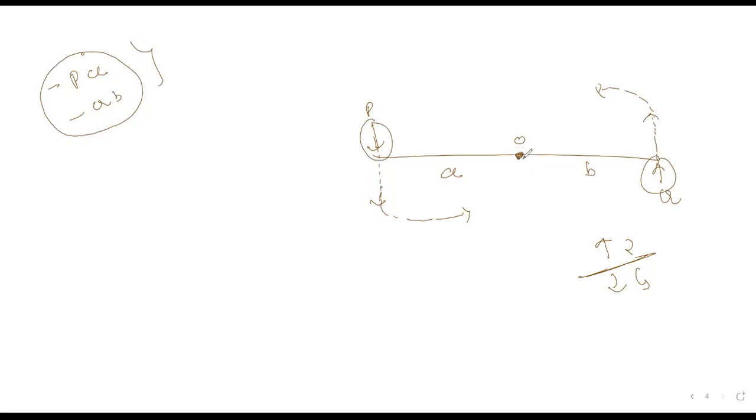Keep in mind, the direction of moment depends on at which point or at which location you are taking a moment. Okay, it depends on that. Fine, both forces have opposite directions, but we are taking a moment about O. Your force is on the left side of point O and we are taking moment about point O from the right-hand side of the force. So we can't say that your upward force always gives a clockwise moment or your downward force always gives an anti-clockwise moment. Okay, remove this from your mind. Is it clear why I have explained this thing? Yes or no? Yes, sir. Clear.